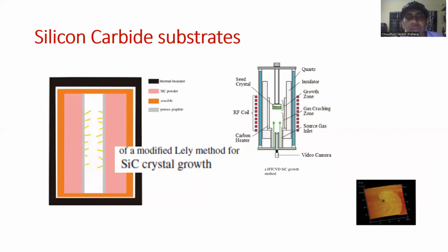Silicon carbide substrate on which we can grow these materials, or we can have silicon substrates. So those are all cost versus device performance considerations that need to be kept in mind while designing solar cells for different application segments.